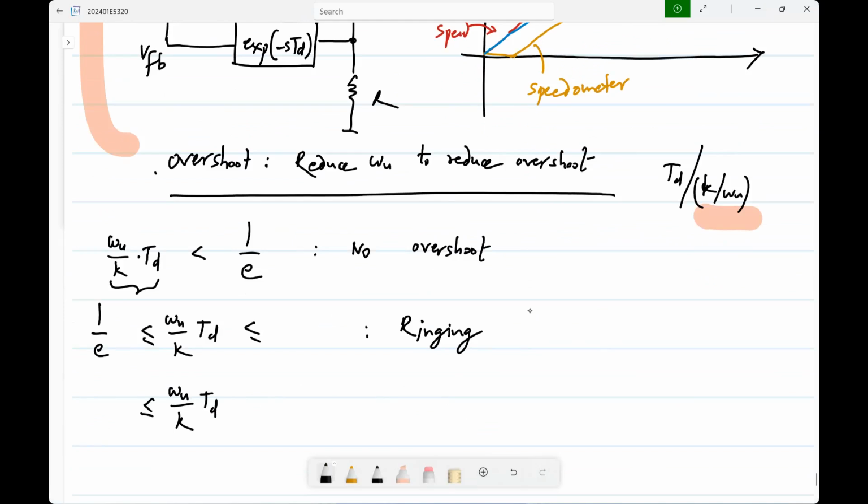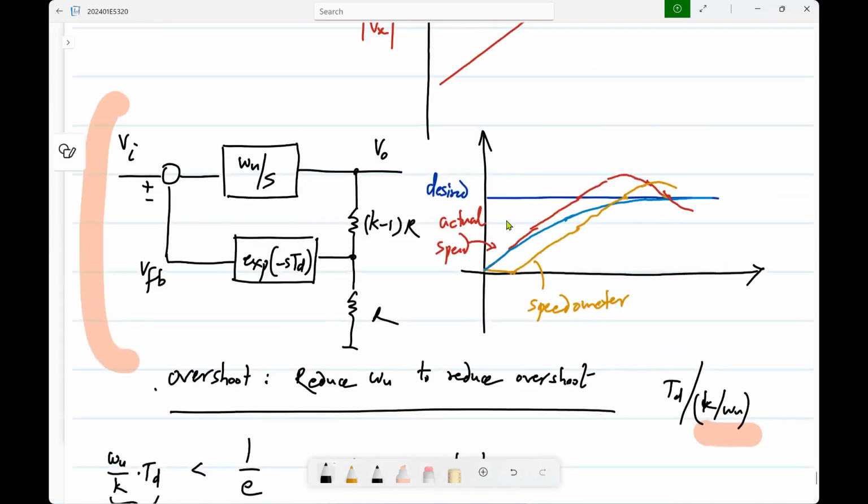What happens is, let's say you want to reach 40 and you overshoot to 80 or more. Okay. And then when you come down, this is a little weird, but you will be going backwards because your speed has become negative. Okay. That is, the ringing can die out or it may not die out at all. With a sufficiently long delay, that's what is going to happen. So you will keep going back and forth forever. It will never reach steady state.